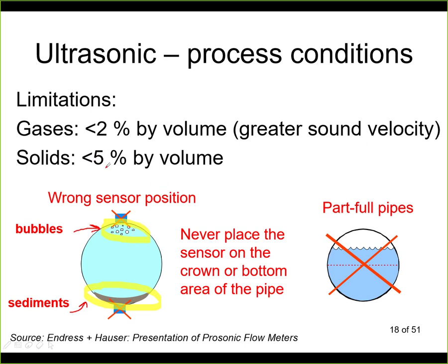If we are talking about solids, again there is a limitation, typically something like 5% by volume, and this is due to the attenuation of the ultrasonic signal on the particles. Installation should be done as follows.